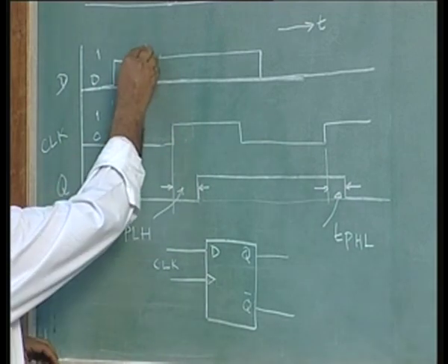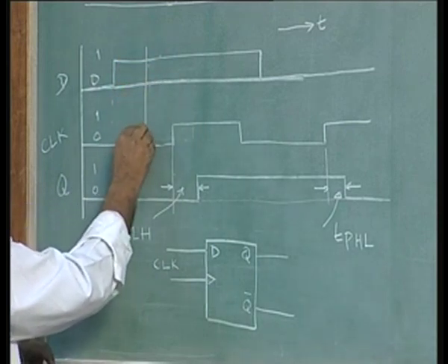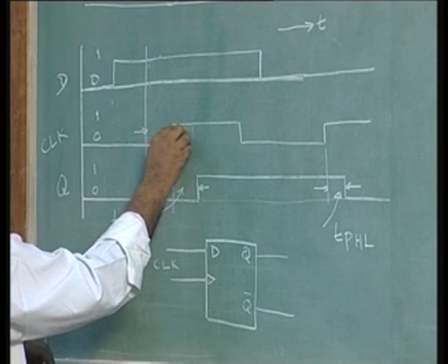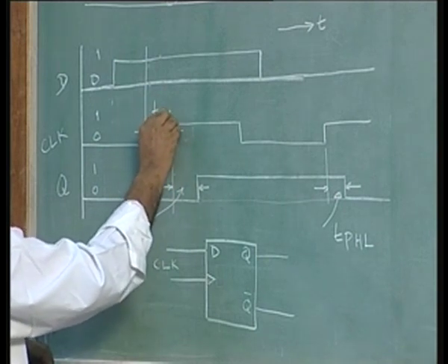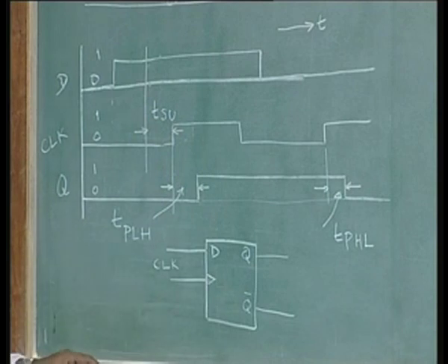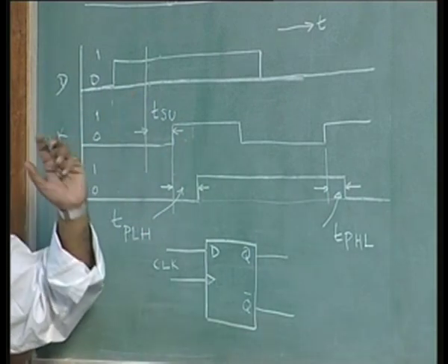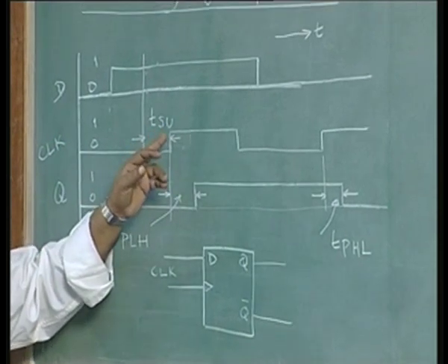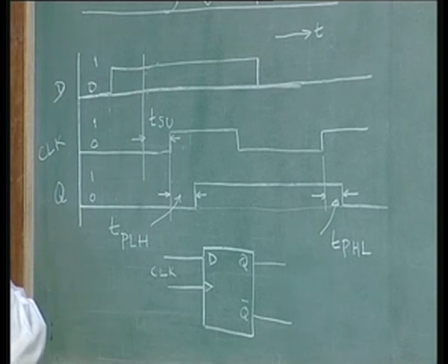So, somewhere here, this interval, we will call this TSU, T setup. The setup time is the minimum time before the clock transition that the input should be stable, or the input of the flip flop. That is called the setup time.